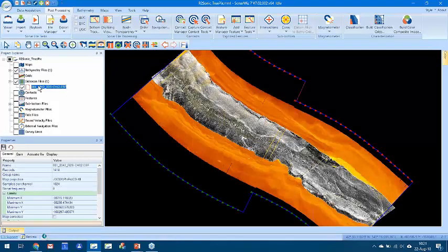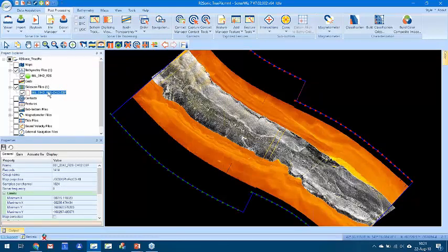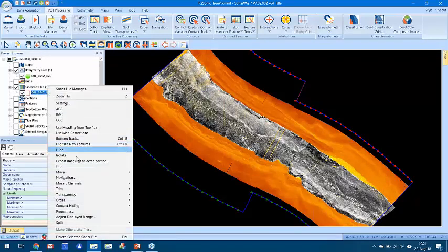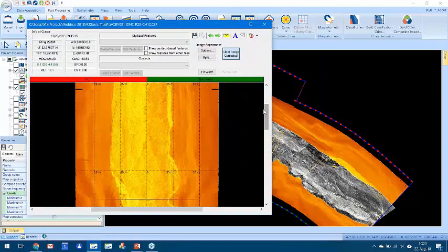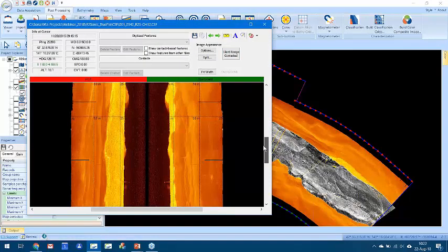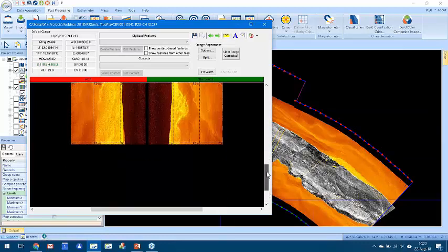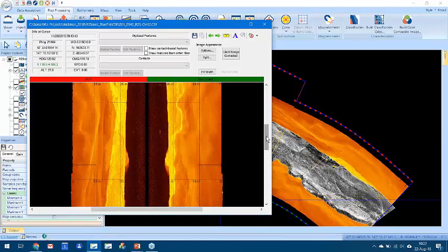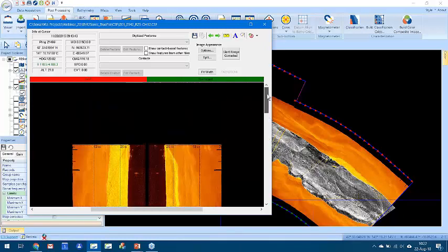But here we imported the same track line, so here's the line as bathymetry and backscatter, and now you've got it also as side scan. So you can, for example, go to the digitized features here. You can see it. There's all the data. There's water column data in this. So it's a very cool data set. It's similar to a side scan in that you have this full range of information, but you have accurate angles, so you know the angle or range to where those image pixels came from.